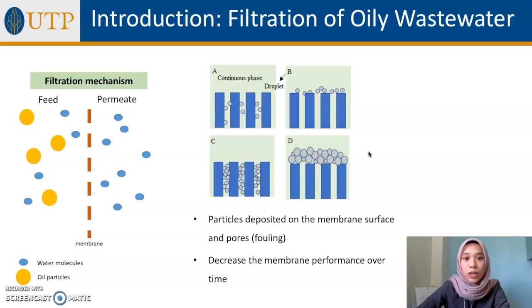So as I have mentioned before, PVDF membrane is a hydrophobic membrane. So the filtration of oil water by using PVDF membrane will easily foul the membrane, as the oil particles will plug the surface, resulting in small filtration and high energy consumption. However, membrane can be modified in order to improve its fouling properties, which is what we want to achieve in this research.